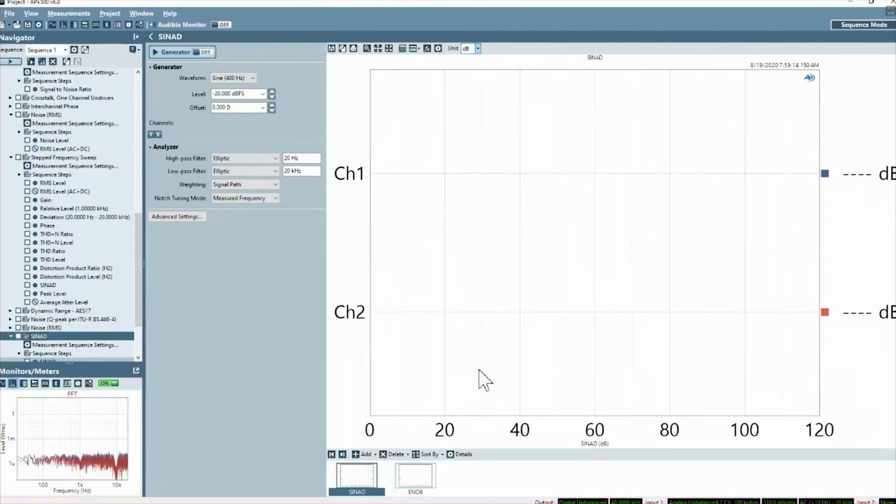So in and of itself, all the same measurements are valid, but there may be some peculiarities to the device itself. So one that I'll say comes up the most frequently is when we're looking at delta sigma modulators. There is, to our knowledge, no delta sigma modulator that can be fed a full scale signal without becoming unstable.